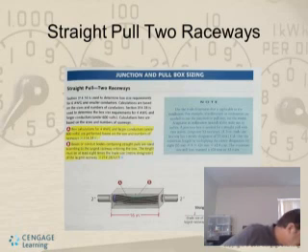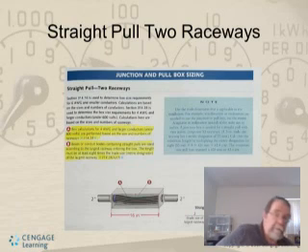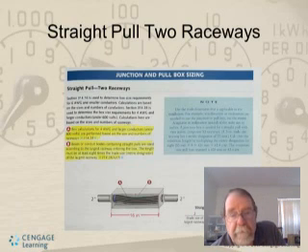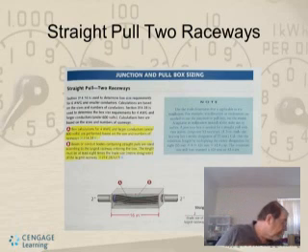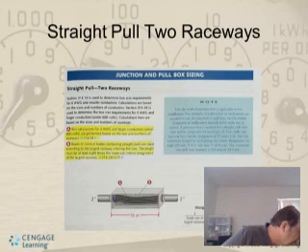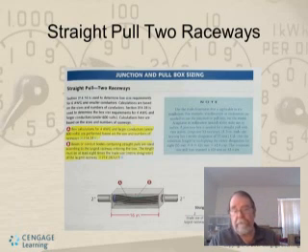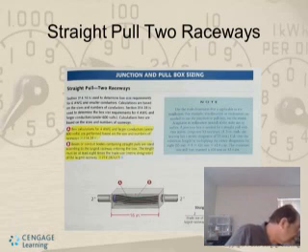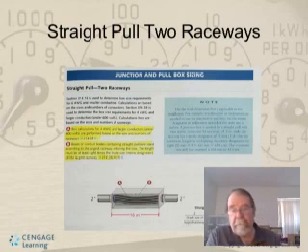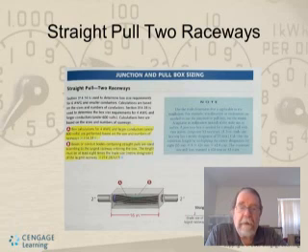Okay. Now, here they use 8 times the millimeter size is what they're talking about. Now down on the bottom right, they show the straight pull, they show a calculation where they multiply it by 8. The raceways, you have 2 of them at 2 inches each. Okay, so that's 16 inches. 16 inches is 42.4 centimeters, I think is what they're getting at with that note. So you need to have room to pull the conductors through, so you can have a box at 16 inches.